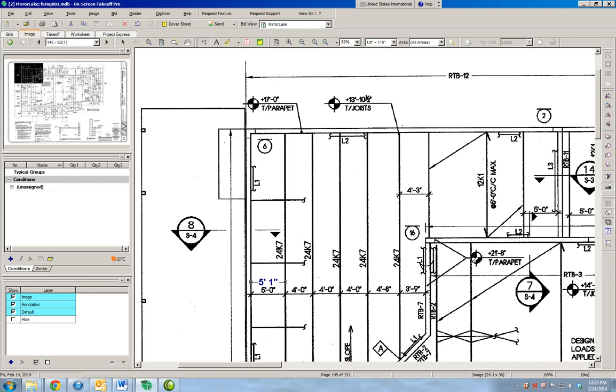For the quantity of work, we'll type the equal sign, go to the OST tab, and select the linear feet that we have for that joist. When we click enter, the Excel file will calculate the material cost, labor cost, equipment cost, and total cost.